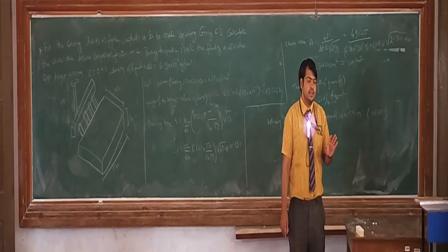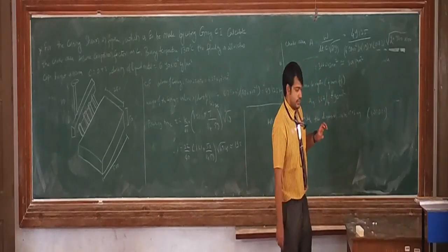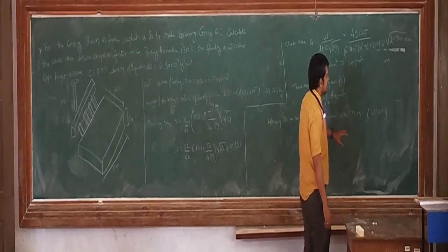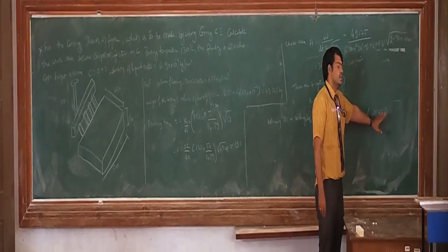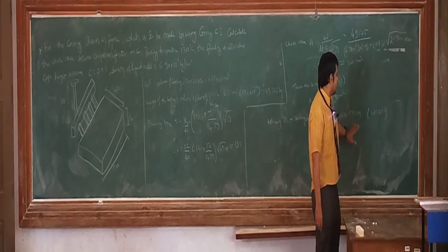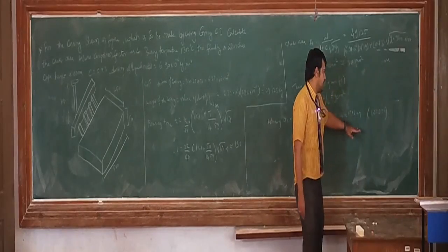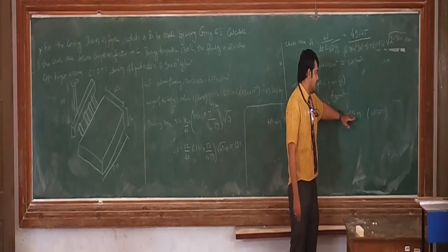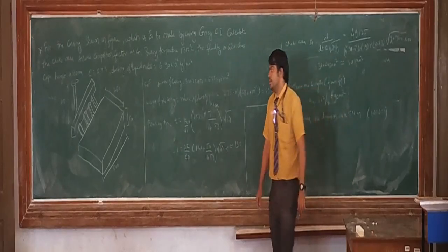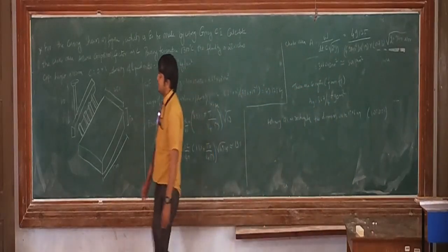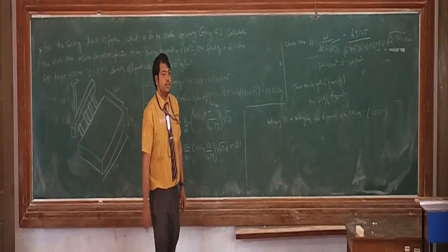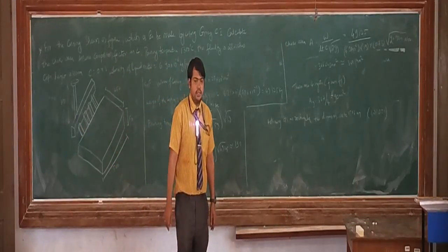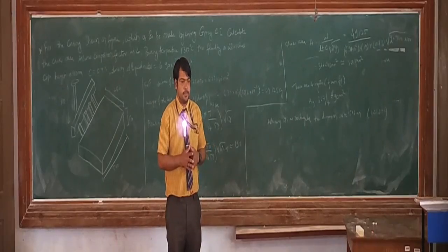Okay. But we have one more ratio which we have discussed in the earlier classes, that W, width, is equal to 2.5 times height. Because of this, whatever we have calculated is 15 by 6. 15 mm is the width and 6 mm is the height of this particular ingot or entire gating system. Okay, this is how we design the gating system. I hope everything is clear.